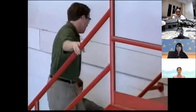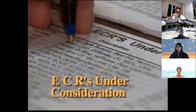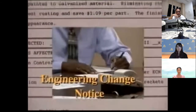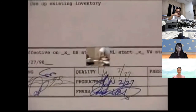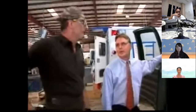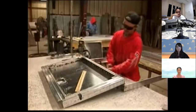On occasion, an error in the bill of materials will surface during production. When identified, a team of Wheeled Coach managers is called in to review an engineering change request. Participation by managers from different functional areas is key, since changes may affect more than production. If the team approves the change, an engineering change notice, or ECN, is signed. The ECN must be processed by the MRP system before the change is made, and the required part is released to the assembly line. Employees also develop ways to improve a part or product. These too must go through the ECN review process.